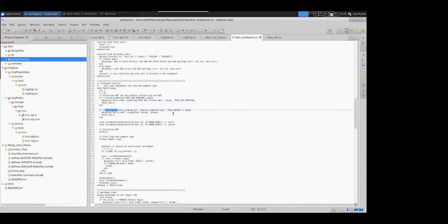And so you'll see here we're configuring it as an RV32 supporting both the integer set and the compressed instruction set. Interestingly, there are a number of other parameters that can be set at runtime as well, and I'll go through some of that, and you can use this to layer on top additional capabilities that are available but switched